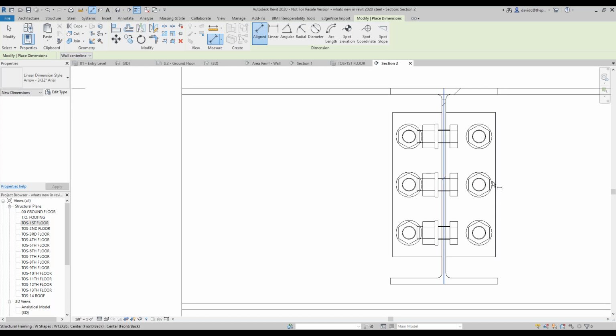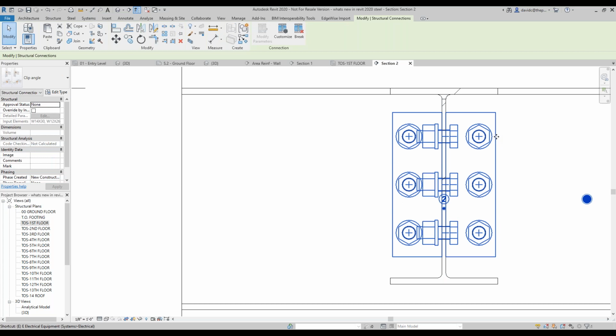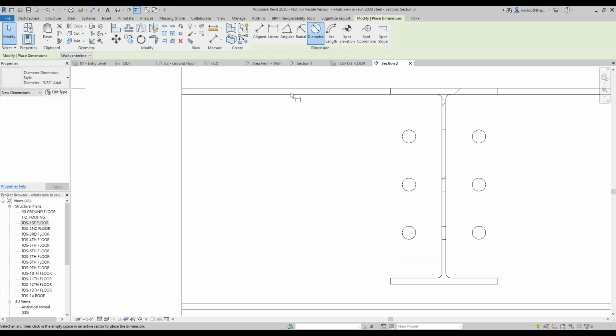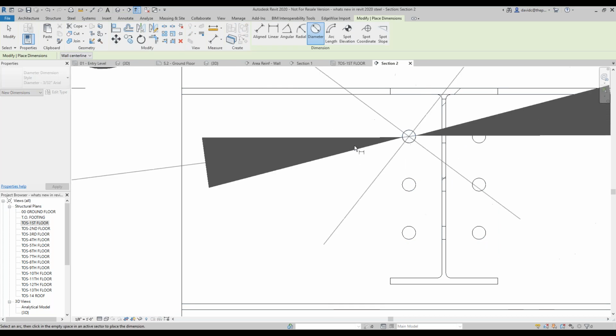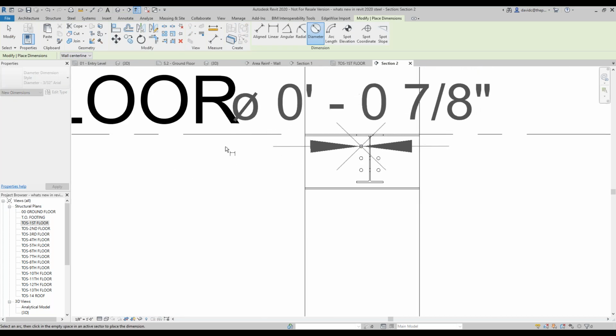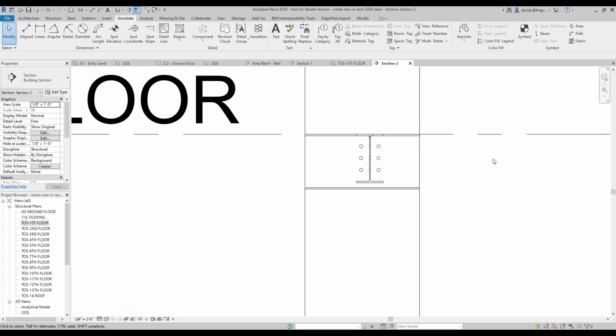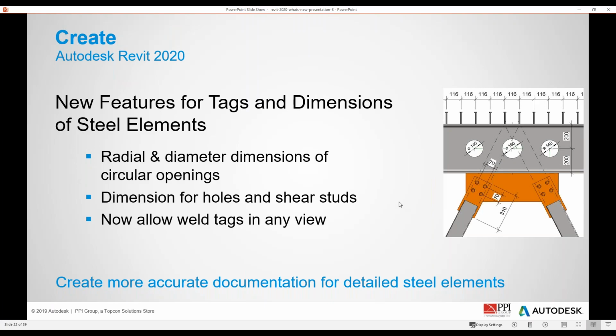Okay, now I'm going to go ahead and show this one as well. Element hide. And I'll jump in here. So if I grab my diameter, you're going to see it will react to my bolt holes and give me my diameter for these holes. So I can go ahead and shoot that out and send it up to whoever needs it.